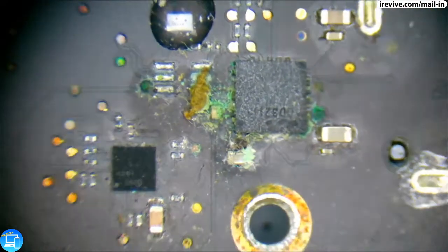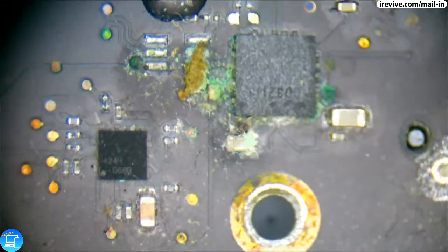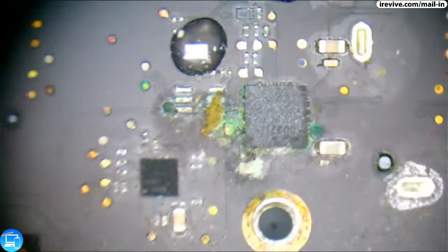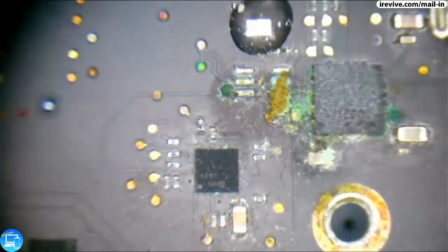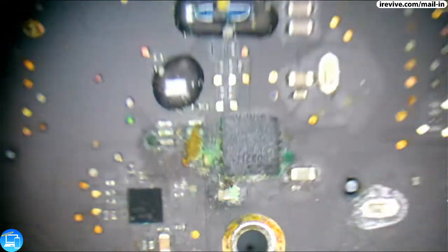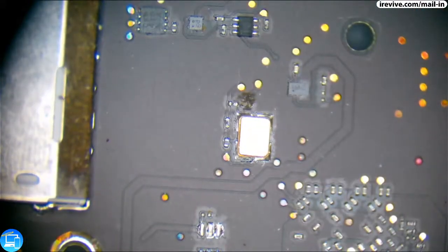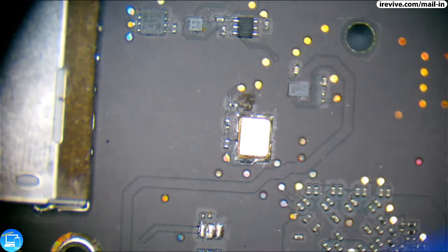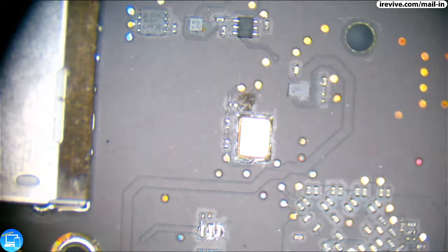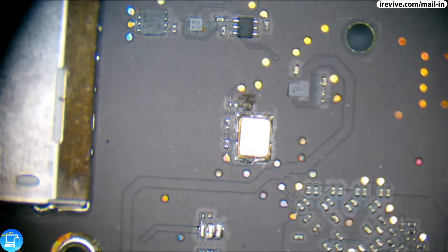There we are. Our CD3211 Thunderbolt port power mux. So let's just replace this after we look around and make sure there's no other signs of damage. What is that? Only thing is, you both know that A1708 has solder on ports. A1706 has screw on ports.